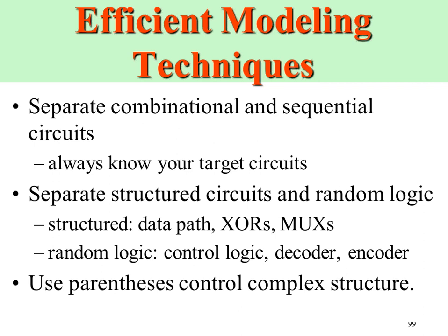And there are certain guidelines. If you follow those guidelines in Verilog, there is a very good chance that the hardware generated will be reliable and efficient in nature. So what are those guidelines? You try to separate the combinational and the sequential circuits as much as you can. Ideally speaking, you completely separate them.